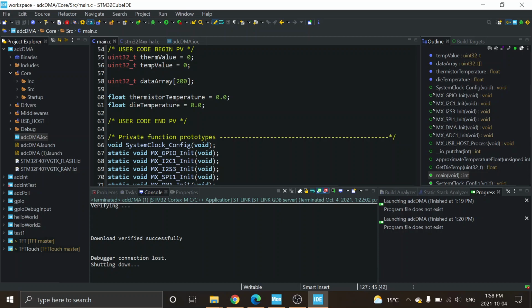Because if I tell the DMA controller to move over to the next 16-bit location, and then I store it as 32, then what'll happen is it'll put two 16s in a 32, and you'll get a really, really big number because it won't be leading zeros at the start. So if I did half word and save that space, then that has to be a uint16_t. When you go and compile it, it will give you a little exclamation mark going, my API says it's a 32-bit word, so you potentially are losing data, and are you sure? Okay, that's what the little exclamation mark will tell you if you go and do that.